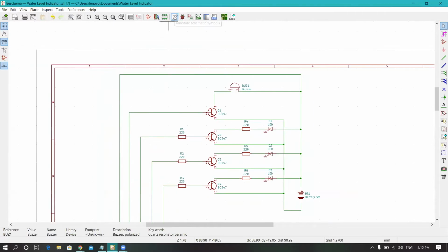So now after doing this, these are the steps we will do one by one. First we have done the annotation. Now we will assign PCB footprints to the schematic symbols. Yesterday Mohit Gupta asked how to define the through hole component or the SMT component. Here is the answer to your question, and this is the step where we will define it.